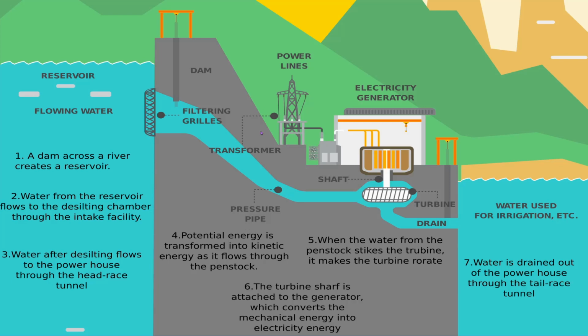And here in this example, the powerhouse and the dam are constructed together, but it depends upon the topography where you want to construct the powerhouse. Now, for a relatively flat terrain like in India, the powerhouse and the dam are usually constructed together. But in our case, the powerhouse is usually constructed way downstream of the dam, because we get a gain in head. We know that our topography is mountainous, and we have very steep terrain.